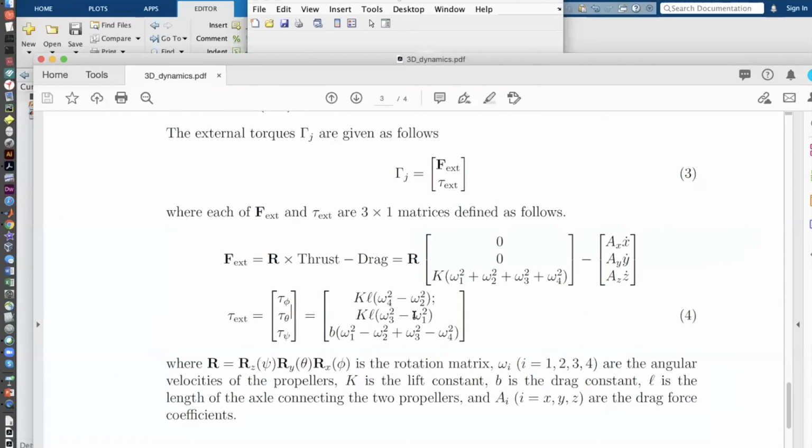when you change omega 1 or omega 3 relative to omega 1, you are inducing motion about the y-axis, but it's also causing this factor to decrease relative to gravity, and so the quadcopter will not hover, but it will crash into the ground. So then you've got to think of how you're going to adjust the other parameters, so that you only get one effect, which is that of spinning, and not crashing into the ground or going up in the sky. So that's rotation about y. I will not do the second part, which is how do you hover and make it spin, but that's something you can figure out.